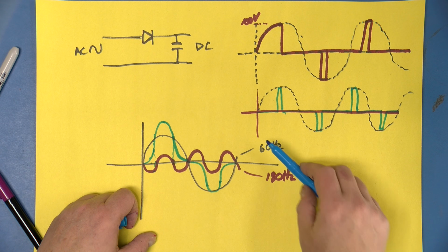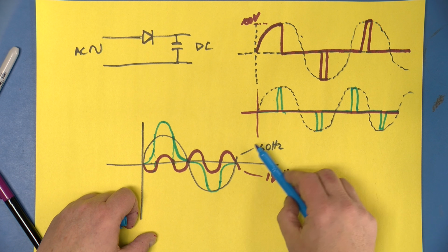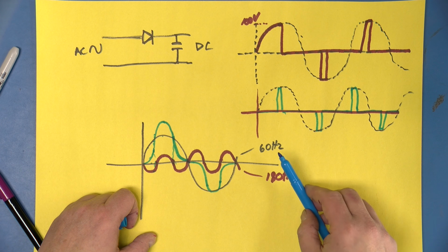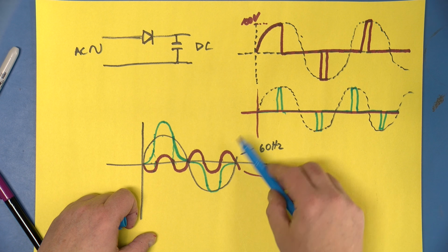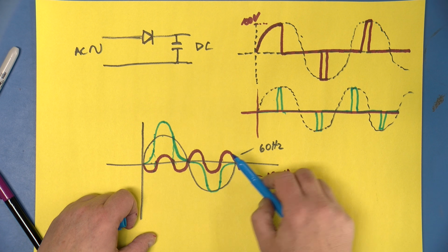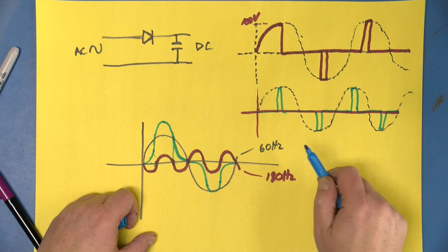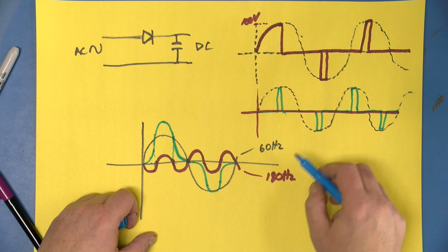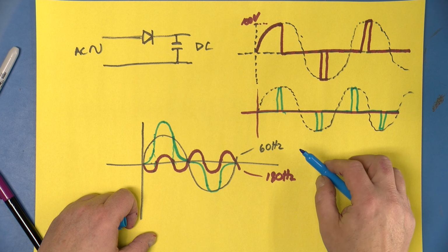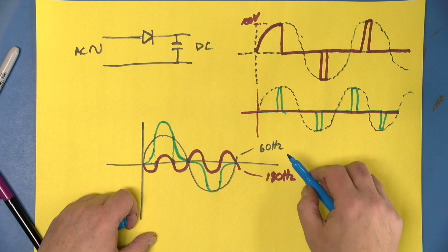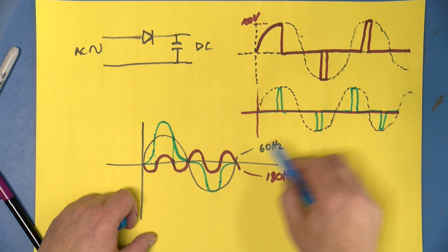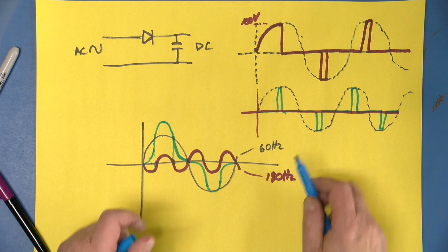For instance, in three-phase transformers, normally the neutral currents all cancel or get very close to canceling. Well, the harmonics at certain frequencies cause those neutral currents to add, and so you get huge neutral currents flowing. You also, in some transformer configurations, get circulating currents flowing. So it's a real problem.